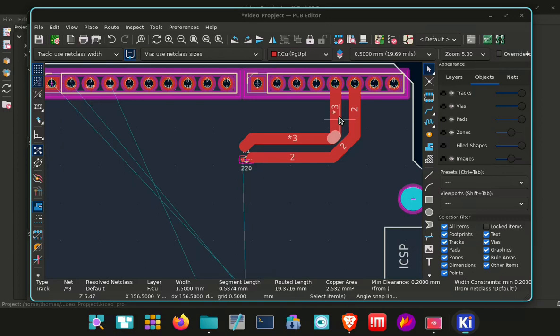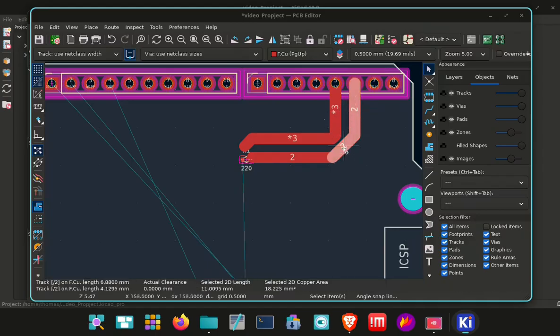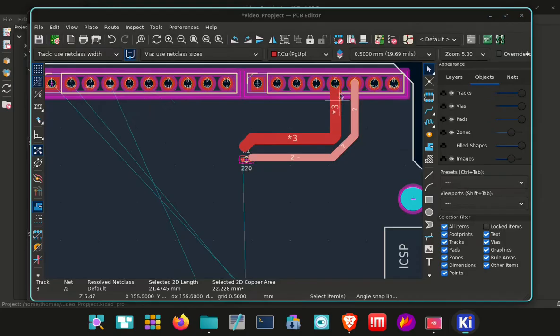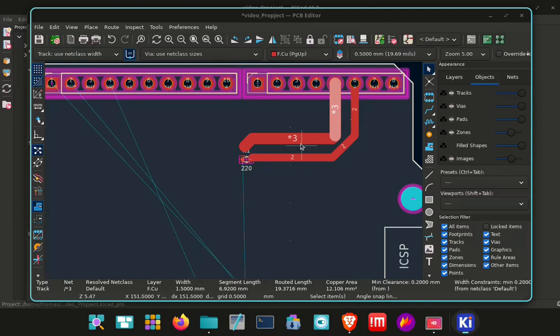There is not enough room for you to get your podger in or your tweezers to actually make that without damaging the track. So that is why we do this at 1mm, and we stick to that, because when they come out of it, when you're over here, make them as big as you like, but when you have to make the tracks in here, it's just too close.